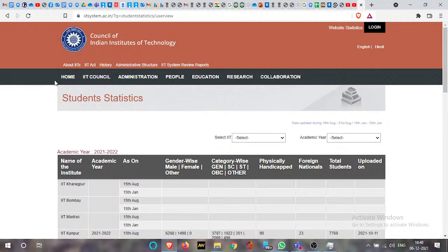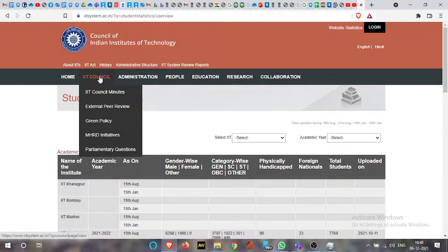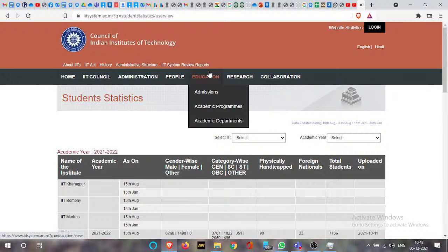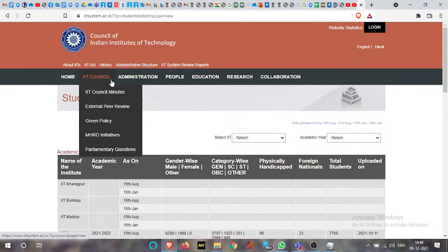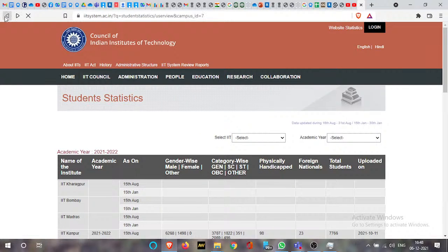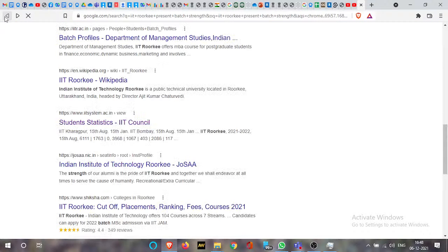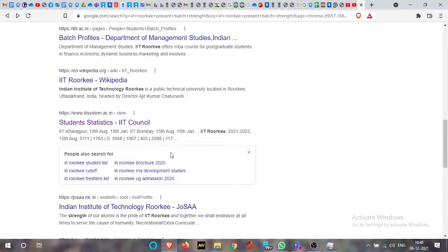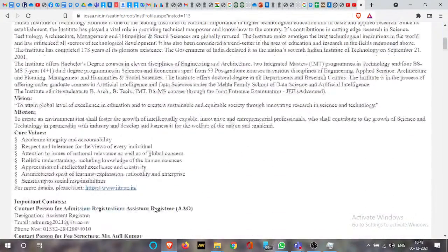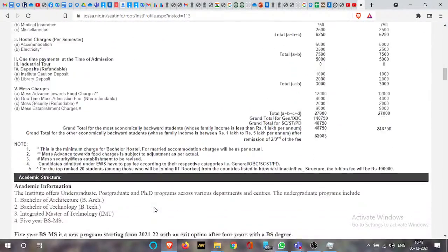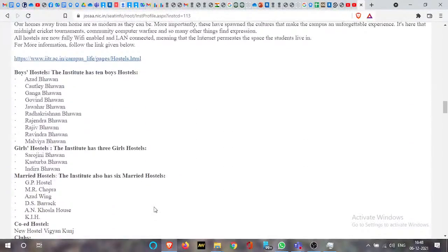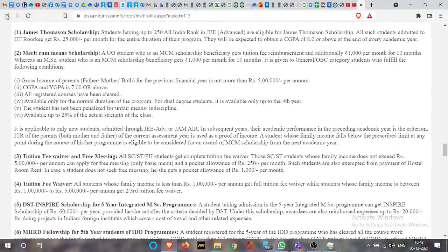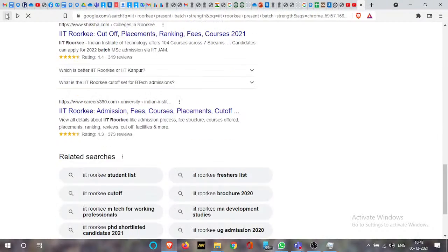And what he observed is that he basically fabricated magnetic tunnel junctions. And why am I calling them magnetic tunnel junctions? Because if you look at this spacer layer here, which is aluminum oxide, this is an insulating layer. So whenever this spacer layer is insulating, it is called a magnetic tunnel junction, because then this effect arises due to the tunneling of the electrons. So here you see it has a different density of states. When you apply a certain bias voltage, it has a different density of states, and because of this different density of states, one type of electron, spin up, experiences a different tunneling, and the other type of electron experiences a different tunneling.